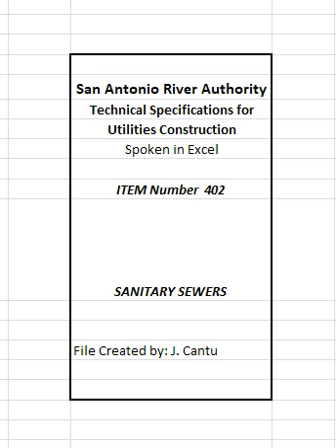Oil separators, which include oil separator gasoline service stations, car washes, garages, dry cleaners, chemical plants, gas plants, hide processors, testing laboratories, or any place where oil or solvents may be introduced into the sanitary sewer system. The sizing criteria for oil separators shall be based on the g.p.m. rate of all fixtures, appliances, or appurtenances draining into the sewer system.